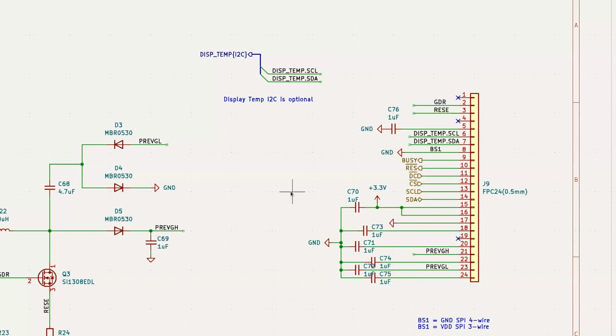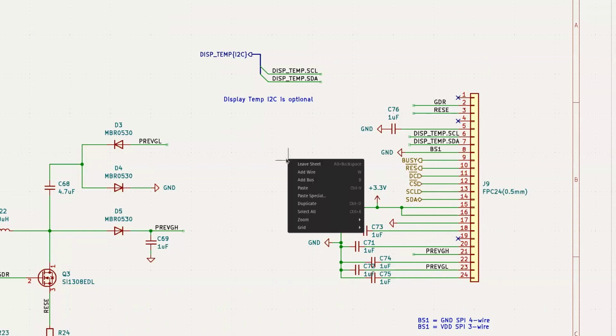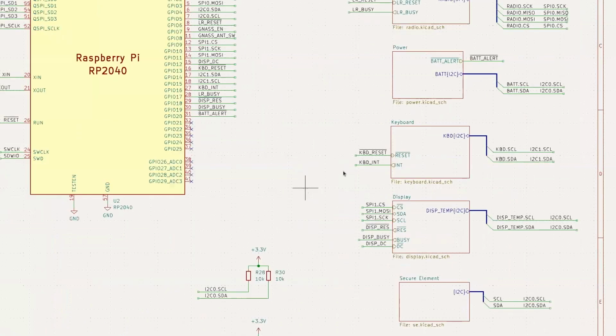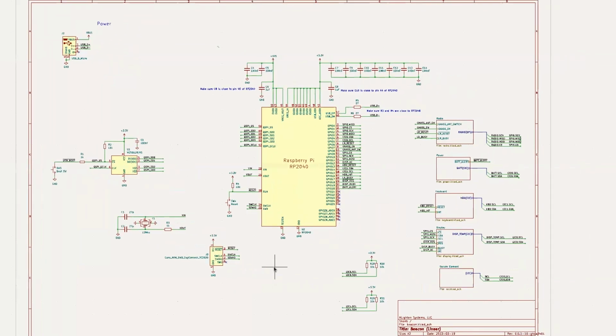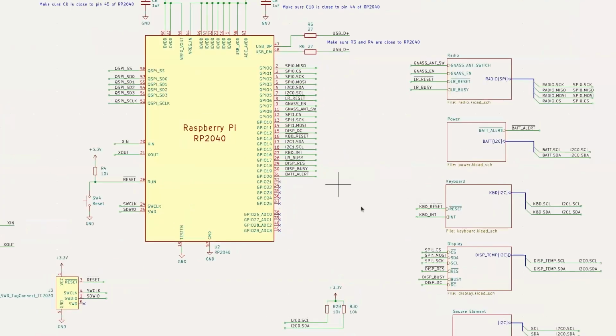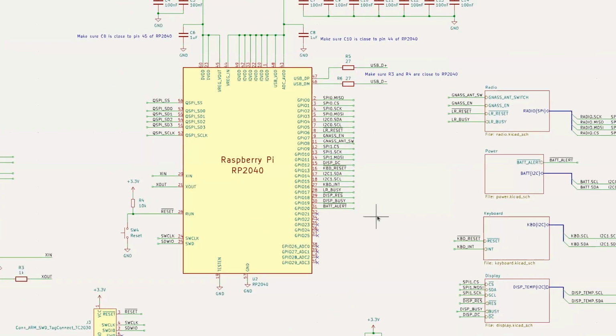Okay, I just wanted to throw that out there. We should think about also single wire debugging. Or are we going to have that on here? Yep, we have that. Okay, cool. Just throwing things out. It's always nice to have an I2C breaking out somewhere, and also a UART. Do we have extra TX RX on the Pi that we can break out? Yep. If I have those, I can get into pretty much any device.